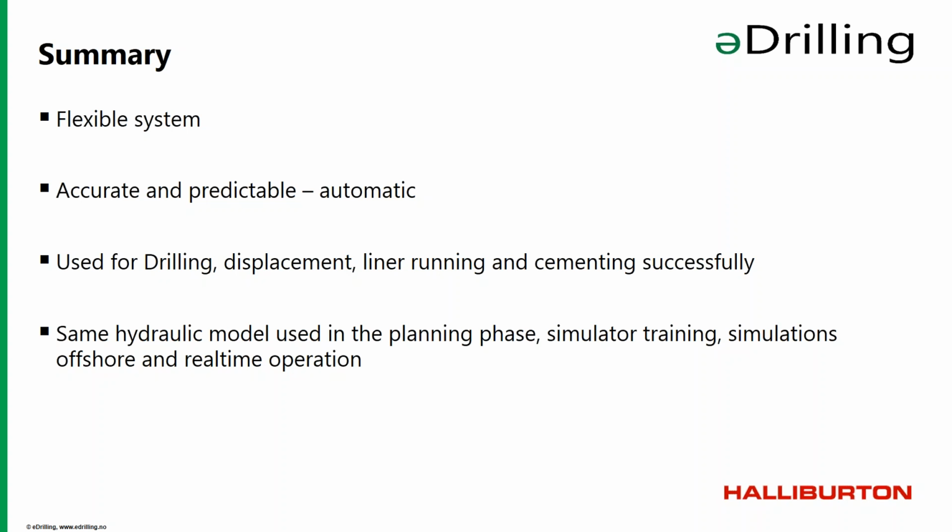Can your model predict the total cuttings concentration in the wellbore? Yes, the model is modeling the cuttings. If you look into the details, we are modeling the cuttings concentration distribution along the wellbore, and we are also modeling what we call the cuttings transport ratio, which is how good it is to transport cuttings at any point in the well.